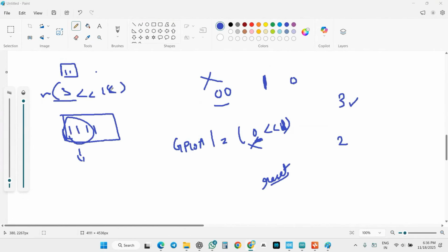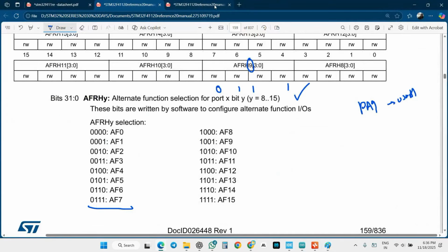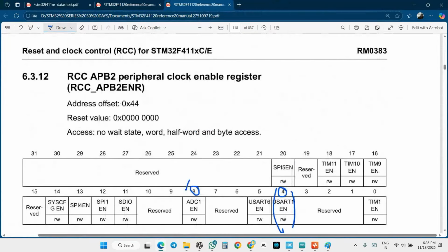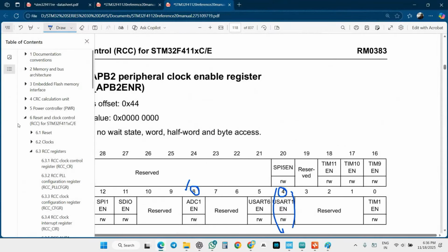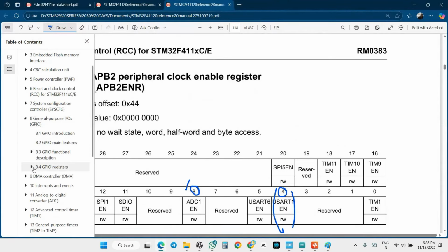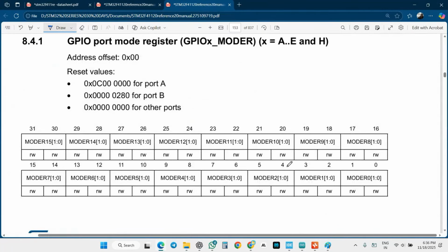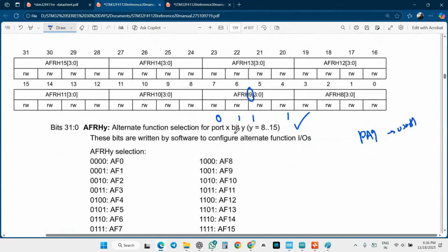So the thing is, I'm simply asking that here I'm going to reset the value. When I'm considering the MODER register, I just reset the value in these 2 positions. First of all, I set the value 1, 1, and afterwards I simply reset it because I need to clear the bits. I use the temporary data of 3 because it is 2 bits. If it is 4 bits, what value are you going to use? So exactly, we are going to use 15.